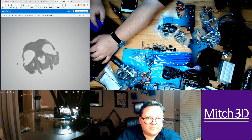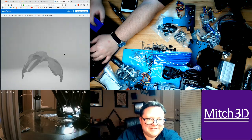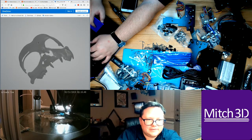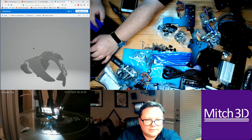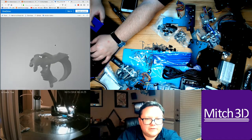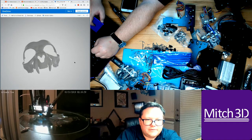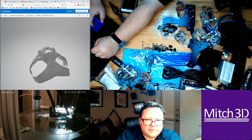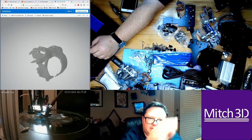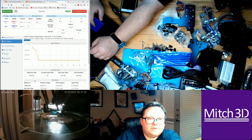Oh my god, that is really cool. Wow, that's going to be really hard to print, though. Oh, man. Oh, there's holes for loops. I'd have to print that at an angle, but I don't want the fangs to be messed up, so I'd probably print it upside down from the brow end down, facing up at an angle like that, and then use support material. I'm going to try that, actually.